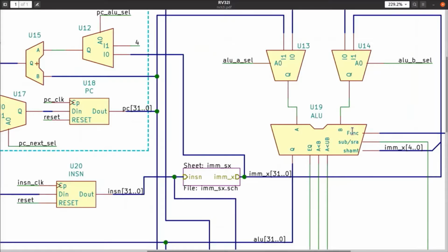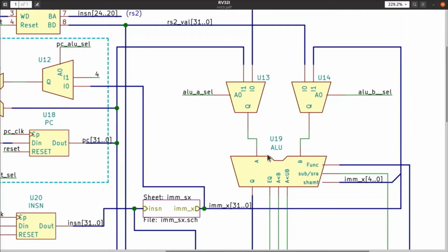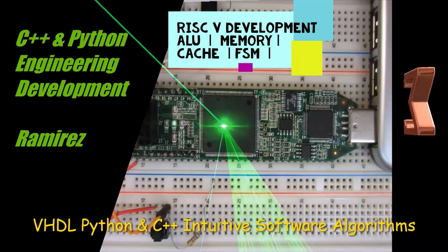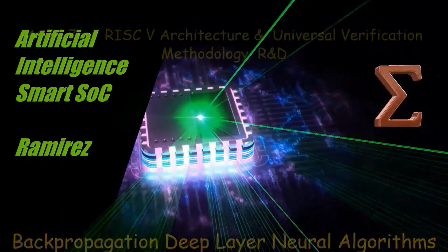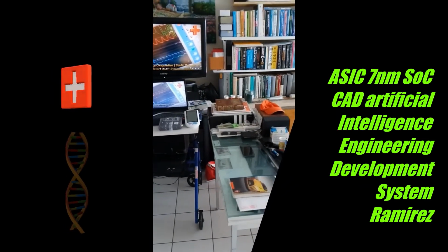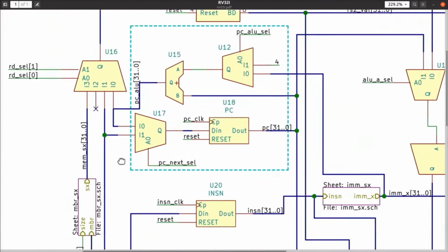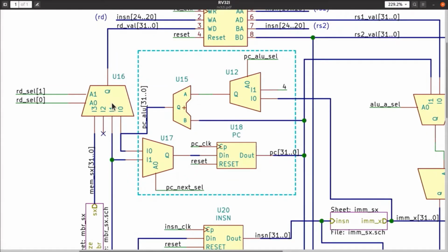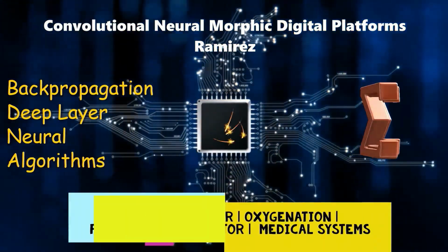Verification files. The entire verification environment, including any bus functional models, bus monitors, or other models, and some set of verification test cases are included with this design. The integrator then develops a test suite to verify the functionality of the macros. So the bus functional models used to develop and verify the macro can be used by the integrator to create a test bench environment for the system-on-chip unit.